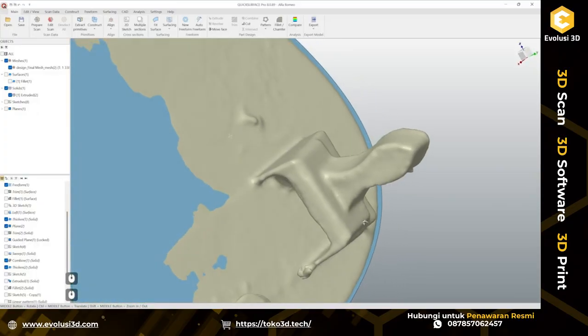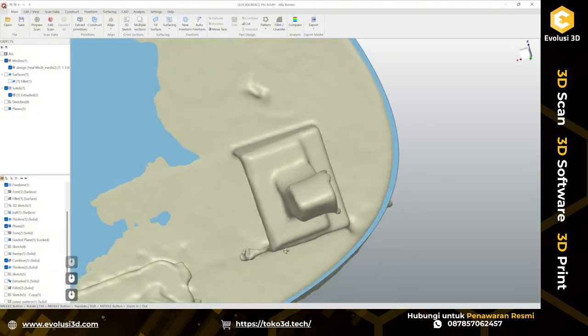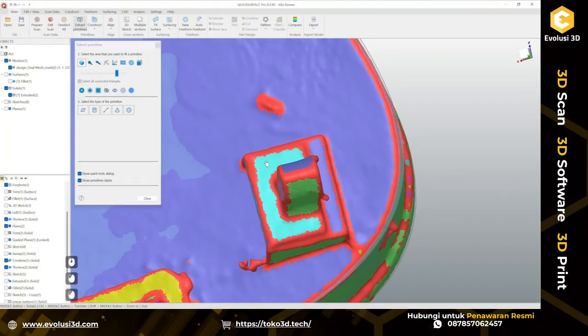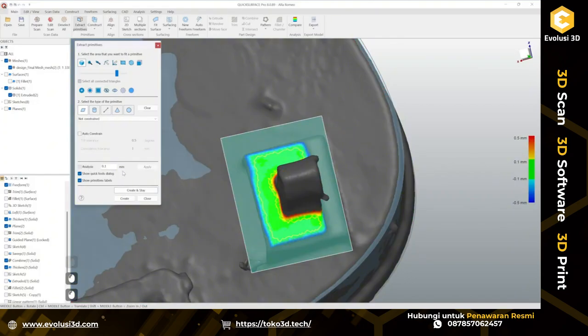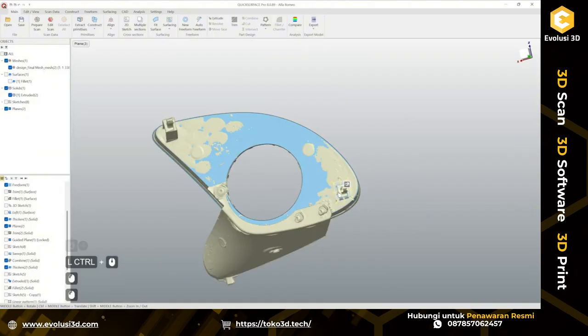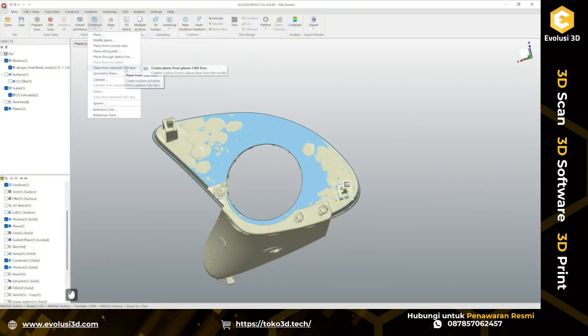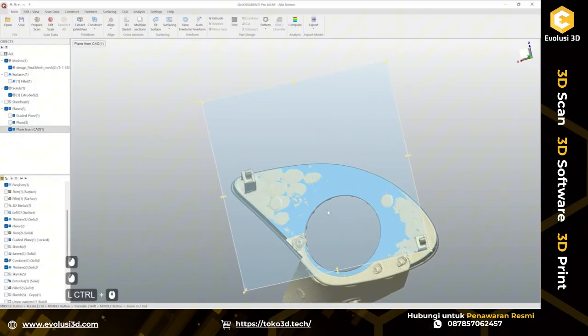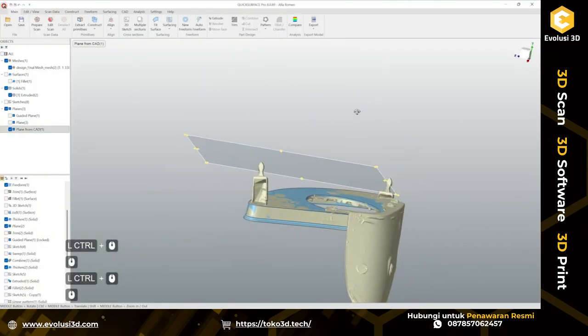Of course, here it's not a super great amount of geometry that we could use, but probably we can try to use this part of the surface here to fit a plane. Okay, let's create this one. Let's select it and say I want to construct a plane from the selected CAD face. At this moment I will hide the initial one. I'll make it larger.